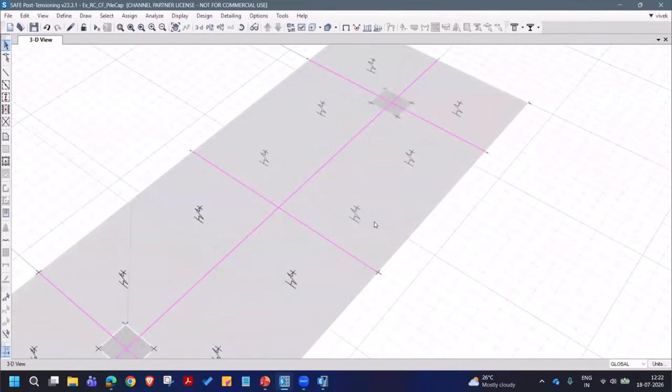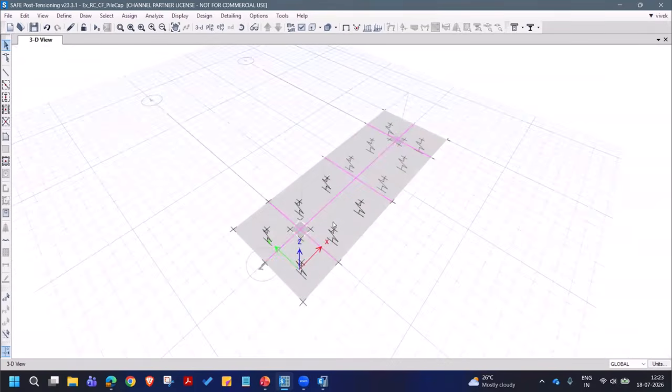In some cases, depending on the configuration of the piles under the pile cap, for example two piles, can create some huge rotations because it has only the axial stiffness, no rotation stiffness for the piles or the point springs. Then it might create some trouble.